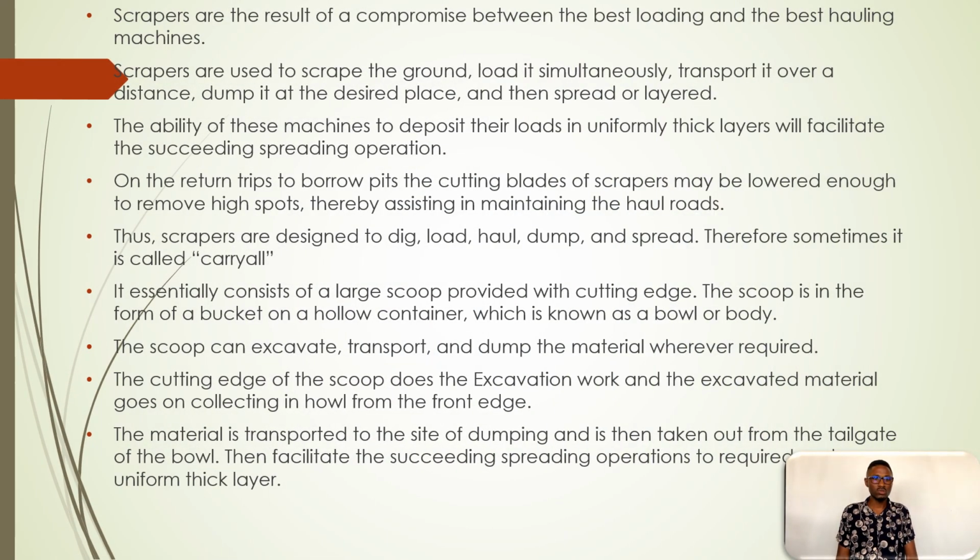I will also go ahead and say scrapers are a result of a compromise between the best loading and the best hauling machines. Scrapers are used to scrape the ground, load it simultaneously, transport it over distance, dump it at the desired place, and then spread it in layers. The ability of these machines to deposit loads in uniform thick layers will facilitate the succeeding spreading operations.